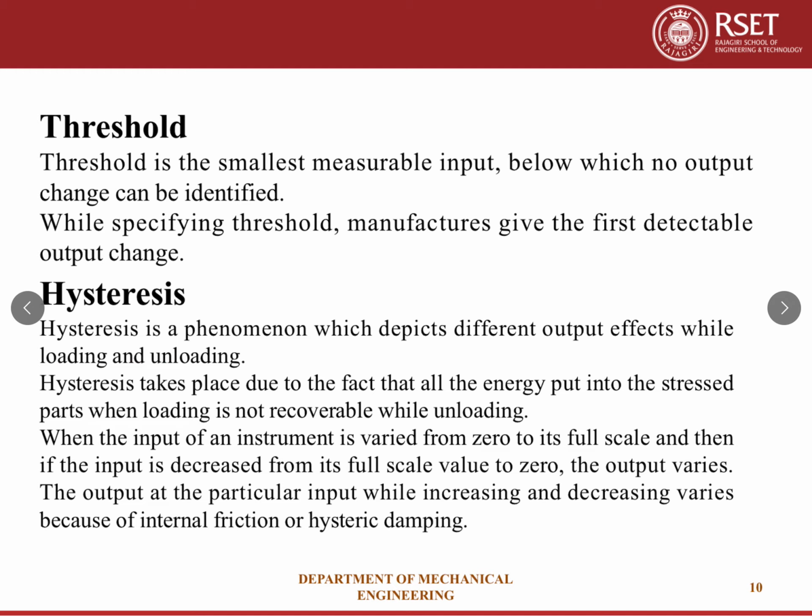This hysteresis takes place because all the energy put into the stressed part when loading is not recoverable while unloading. It remains as some residue in the instrument, and because of that residue the reading will be different. Example, a flow meter.